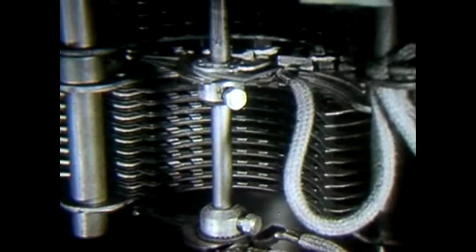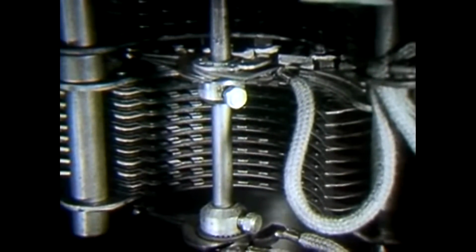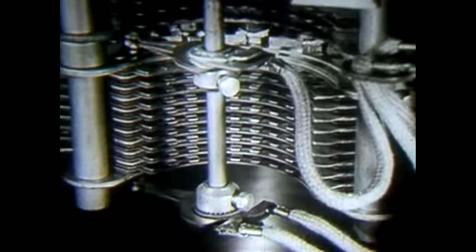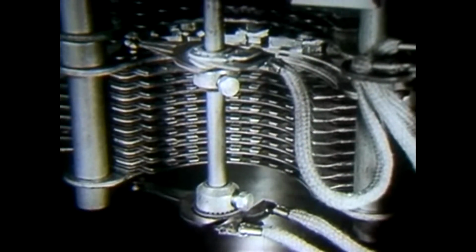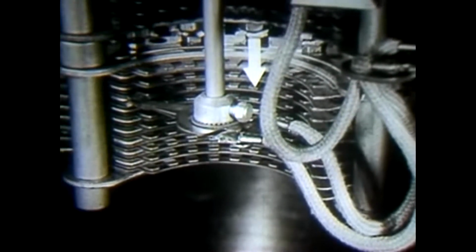As the dial is moved to the finger stop, no action takes place in the connector. But when the finger is removed, the connector will respond to the dial pulses and step up to the 8th level. Notice, however, that it did not cut in. This is because it is now necessary to select the called party's terminal in the connector bank.